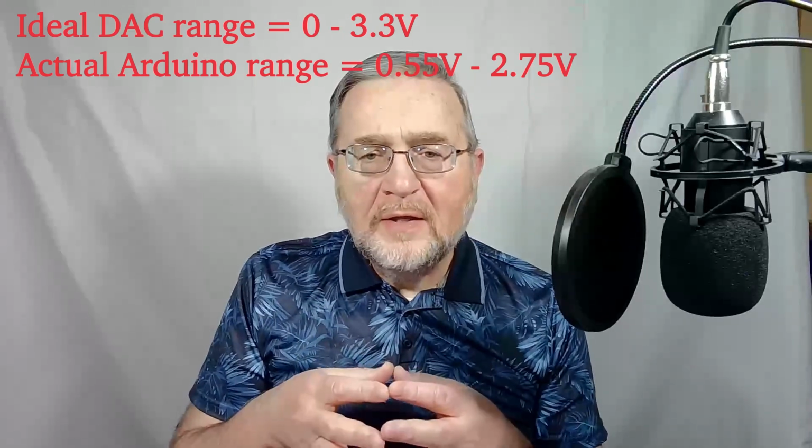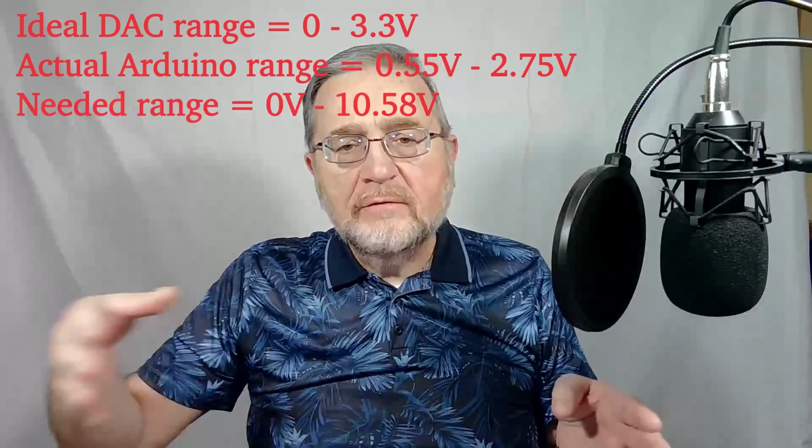Moreover, we actually need a range that goes from 0 to over 10 volt. To satisfy our requirements, we need to do two things then. One, translate down the output voltages by those 0.55 volt, so the range will actually go from 0 volt to 2.2 volt. And two, we need to amplify the final output so the range can be actually extended from 0 volt to exactly 10.58 volt. We have seen already the circuitry necessary to do that in the schematic.